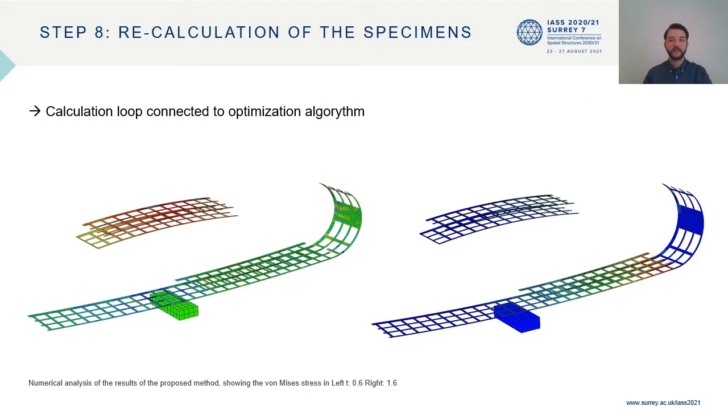And the final step implies the recalculation of the specimens. Since locating the reinforcement changes the stress distribution, all processes should be repeated with the calculated reinforcement, in which the amount of the calculated forces and the related dimension of the reinforcements are considered. The picture shows the beam's performance in which the calculated additional reinforcement is regarded, and a carbon mesh reinforcement is assigned.